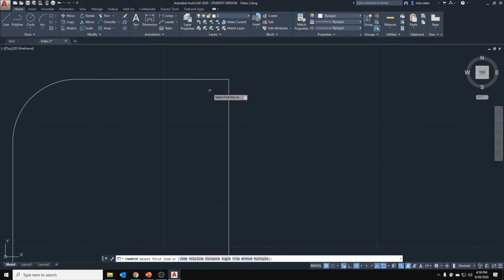What it'll do is, instead of drawing a circular or radial arc, it will draw a straight line between points. That can be between distance A and distance B, or distance A and a degree. Hey look, I rhymed. Isn't that awesome? So in this case, I want to go maybe this distance. A quick way to measure things is honestly just to use line, and not actually make the line, just press escape, but you can get a dimension there. So I'm going to go 0.5. That'll work pretty nice. Press escape to get out of that.